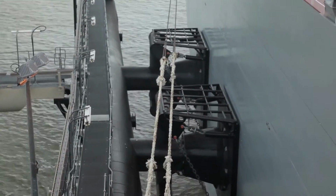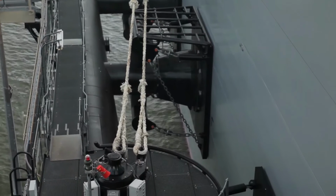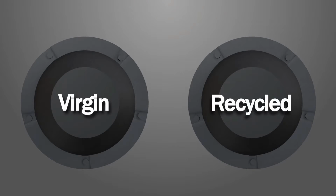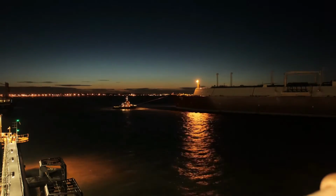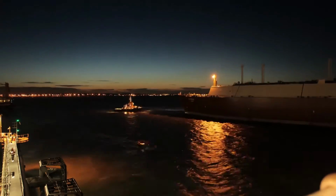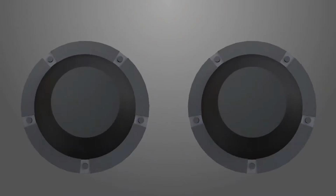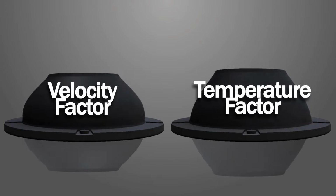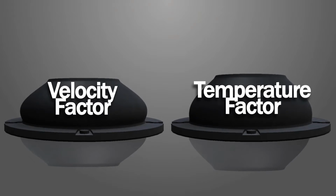Fender performance and life cycle vary dramatically based on the type of rubber used, natural or synthetic, and virgin or recycled, and the compound composition of the rubber. Compound composition has a dramatic impact on velocity factor, temperature factor, and fender life cycle. Highlighted the importance of velocity factor and temperature factor in the design and selection of fenders, and introduced guidelines for